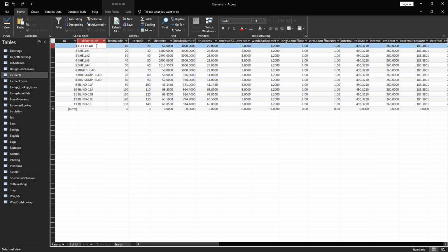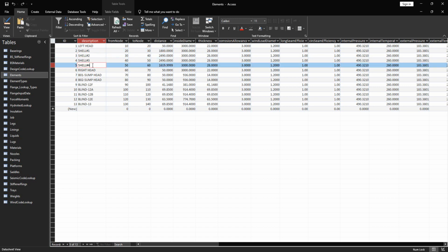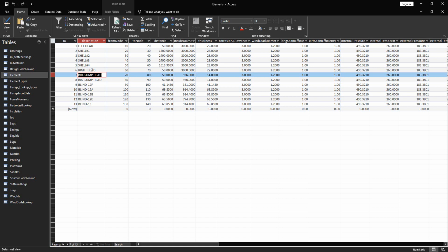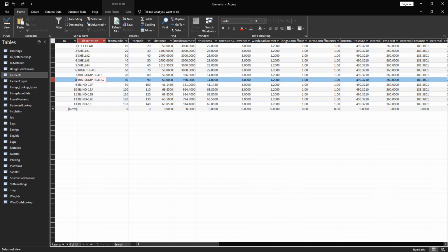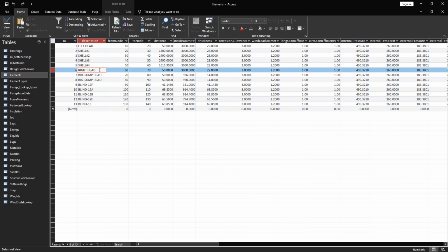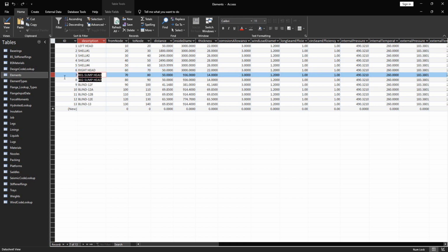Here, as you can see, the first element is the right head, which is from node 10 to 20. Another shell. After that, another head. Now after this head, which is the right head, you have two other heads. That means those heads should be connected to another element. You will not find in a real case a head connected to another two heads in that way.